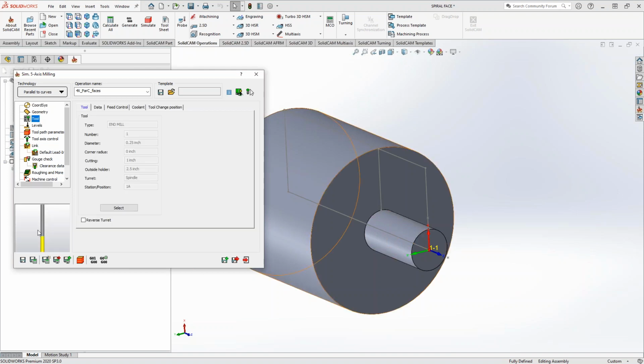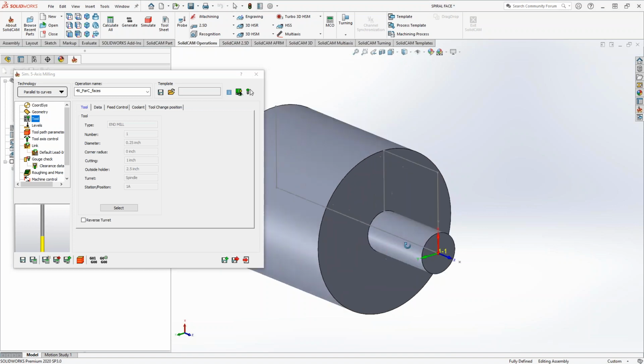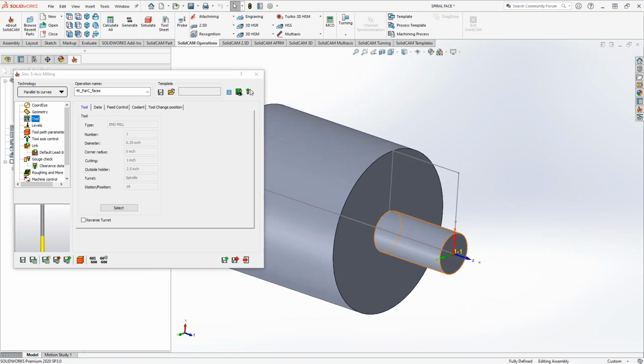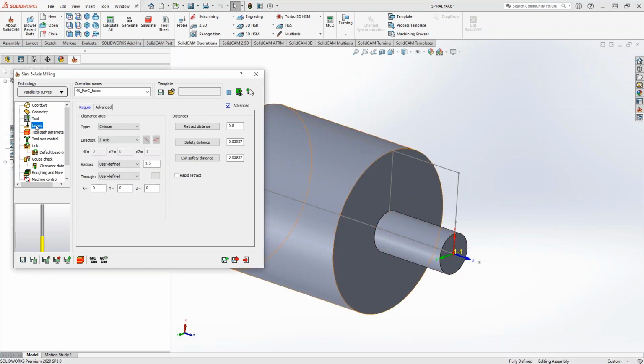In terms of tool, it's the same tool. You'll notice though that I'm not using macro in position 2 in this case. That is because this is a simultaneous toolpath. So it actually still needs to use that same parent toolpath, that same parent macro there, macro in position 1. I'm just going to tell it how to orient the tool in this multi-axis toolpath.